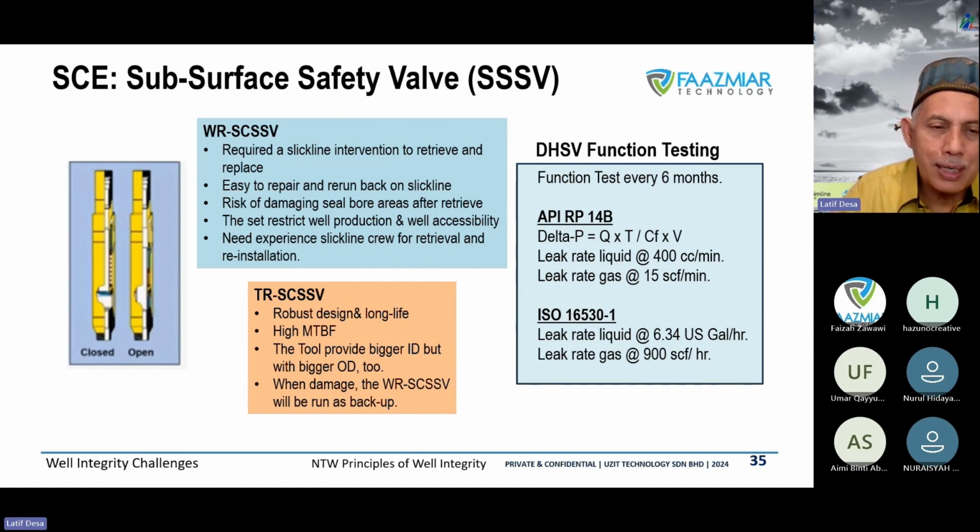But to get a full, good cross area, then you talk about tubing retrievable. Tubing retrievable is like you're setting the triple SV as part of your tubing, so you have the biggest possible cross flow. But of course, if there is any leak, you cannot pull the triple SV because it's part of the tubing. That's why you start to have the wireline triple SV go in as a sleeve and make it an alternative or another option to have this system in place for production.